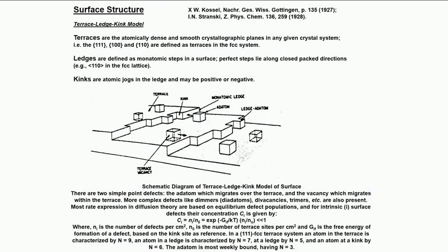Now, another phenomenon observed on the surface is the atomic arrangement of the surface. You will find that the atomic arrangement of the surface is a little different from that of the bulk. As I mentioned, depending on the availability of energy, the plane along which the surface will be created will vary. Usually it is an atomically dense plane along which the surface is created, because it requires minimum energy to create the surface. Now, if you see the surface atomic arrangement, again this is not ideally smooth in nature. There are always discontinuities in the atomic arrangement of the surface.